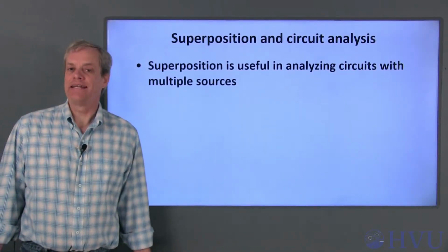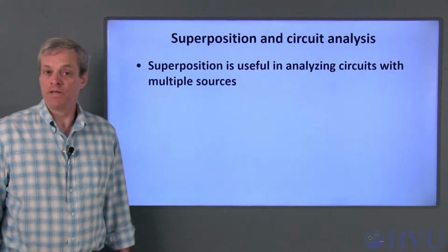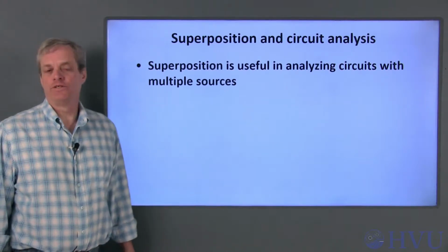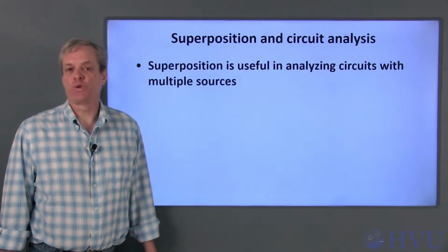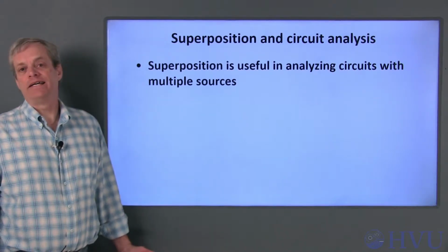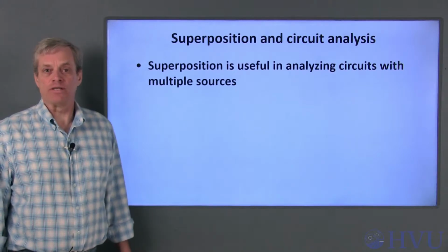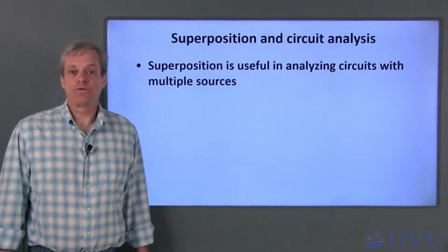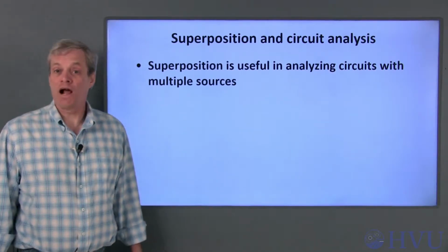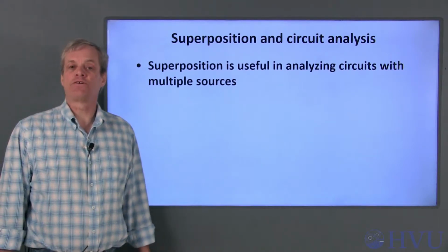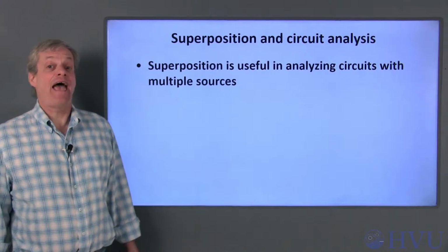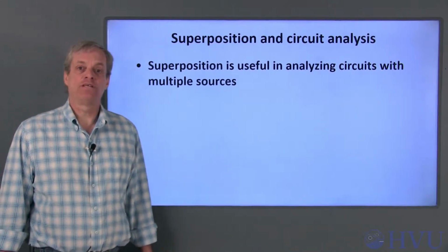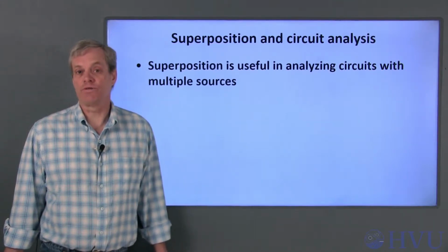Superposition is used a lot in the analysis of engineering systems, but I'll focus on one particular use at the moment, which is analysis of circuits with multiple sources. Power supplies can be considered to be inputs to our circuits. If we have multiple power sources in a circuit, this property means that we can calculate the circuit response to each power source individually and then add up the individual outputs to get the response to all the power sources.